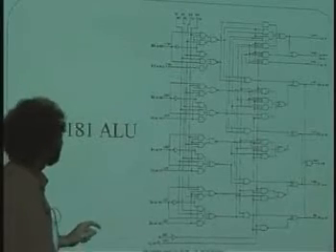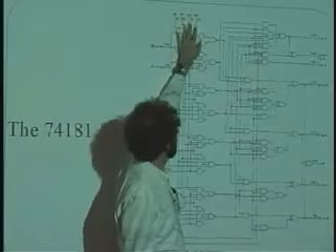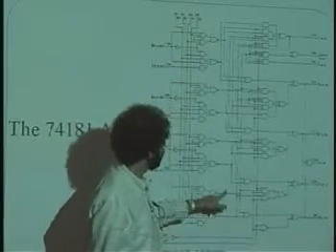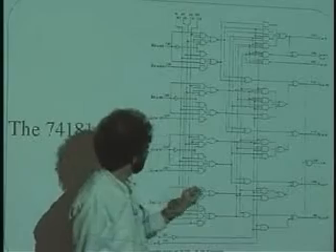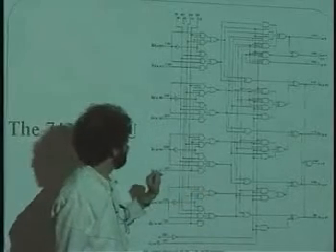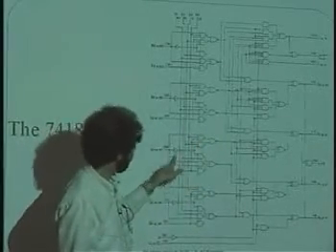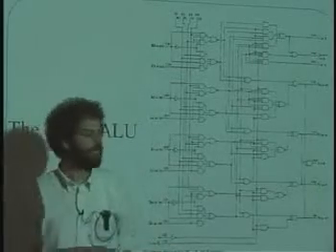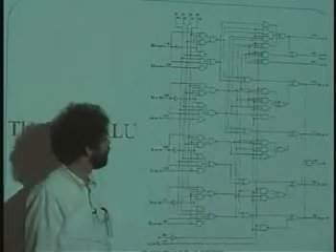And it turns out that if I just fix this code with the code for add, what you would find is that the G and the P that gets generated by the logic function right here, and notice this is a sum of products form. Here's the OR gates, here's the AND gates, here's the NOT, right? Each of these things will in fact be the generator for doing G and P.